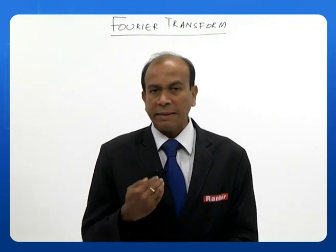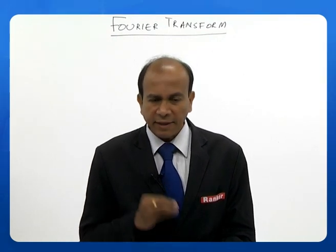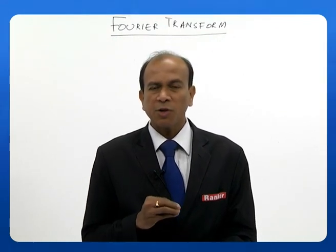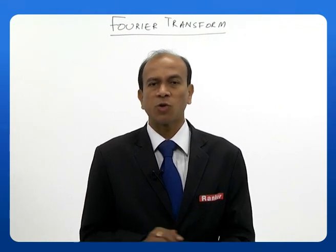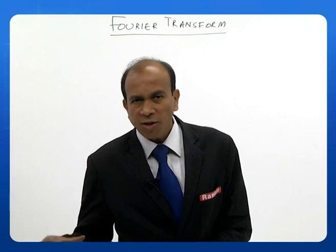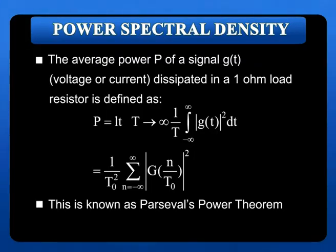So when I talk in terms of the frequency domain, this can be written as 1 by T naught square summation n is equal to minus infinity to plus infinity mod of g of n by T naught whole square. So when I sum all these components, I will get the average power of the signal. This is called Parseval's power theorem.